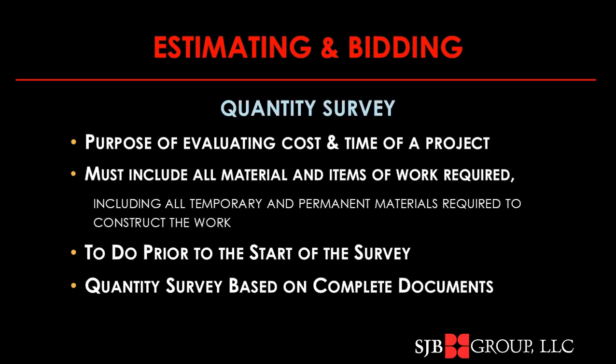Prior to the start of the survey, we're going to have to review the instructions to bidders, the contract, the technical specifications, the general and the special conditions, and the proposal form, because all of those will affect the way in which the work must be done in your takeoff and how you assemble your bid.